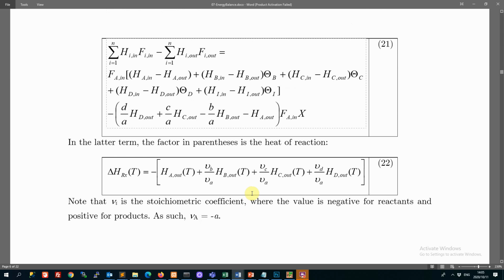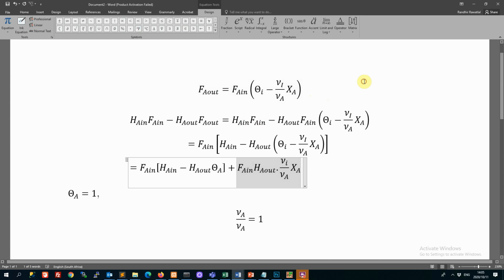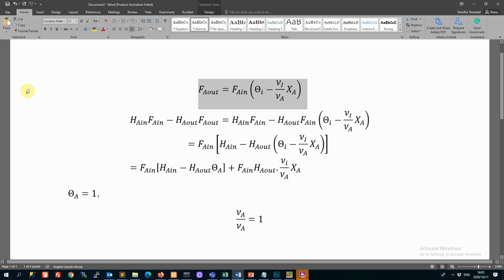So that's again why I say that if you go and add a heat of reaction term to your energy balance, you are double accounting, right? The heat of reaction actually arises from the difference between the inlet and the exit flow. In fact, if you think about it, when we first wrote this part, we just wrote this down quickly because we knew we needed to expand for F A out. We wrote this part down and it's written in terms of the actual inlet flow of component A, and then there's another term that accounts for the change in A due to reaction.